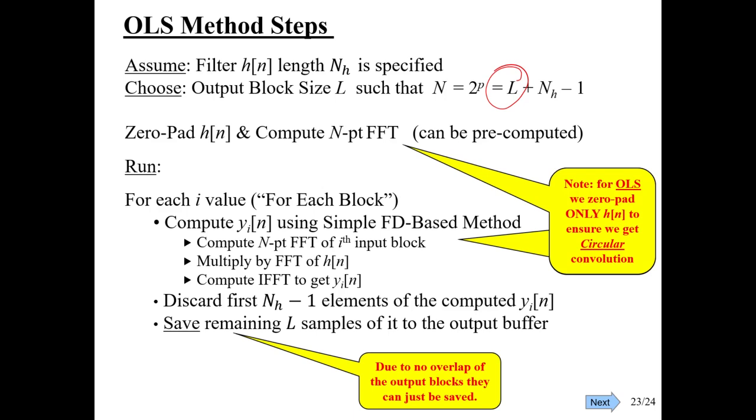Might not be exactly the same, but it's very, very similar. I've never really done that analysis to see, but I suspect that there's not a big difference between them. If there was a huge difference between them, I think you'd see that people would present one and not the other. So either one, I think, works just as well. Like I said, in Gardner's algorithm that we'll see in the next note set, he uses overlap save. I think that's largely just because it is more easily mechanized for that more complicated algorithm.